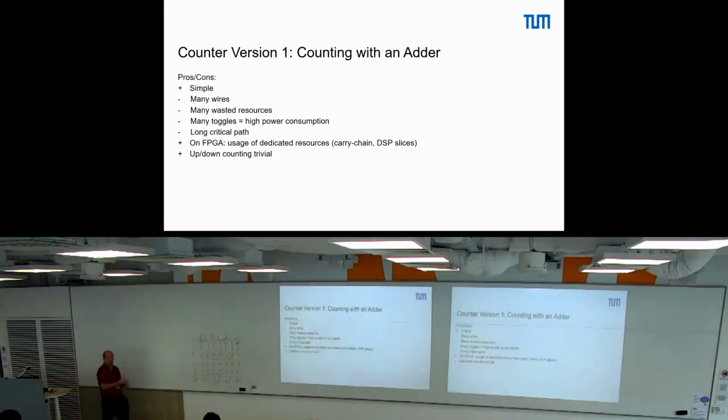So we have already an adder, right? So with an adder, if we always add 1, we can also count, right? So why do we want something special? The main reason is, well, we can easily, with our adder, count up and down. We have maybe FPGA specific resources for that. But since we have a full-blown adder and we do something very specific, we waste resources.